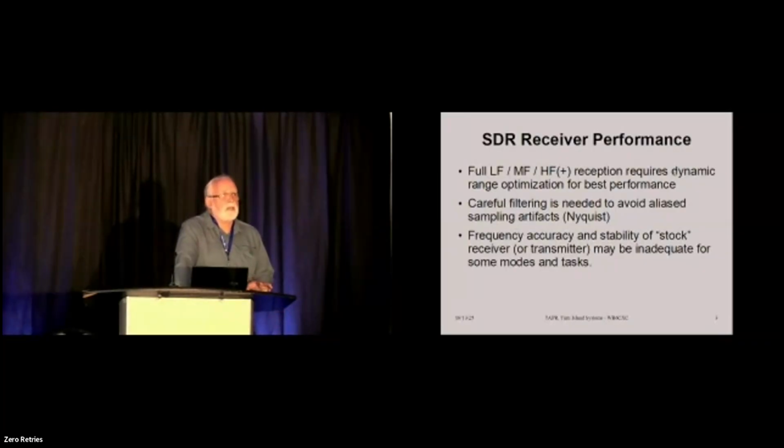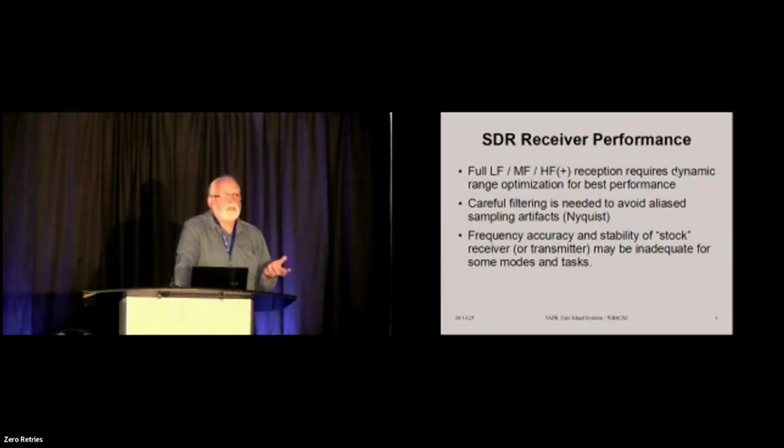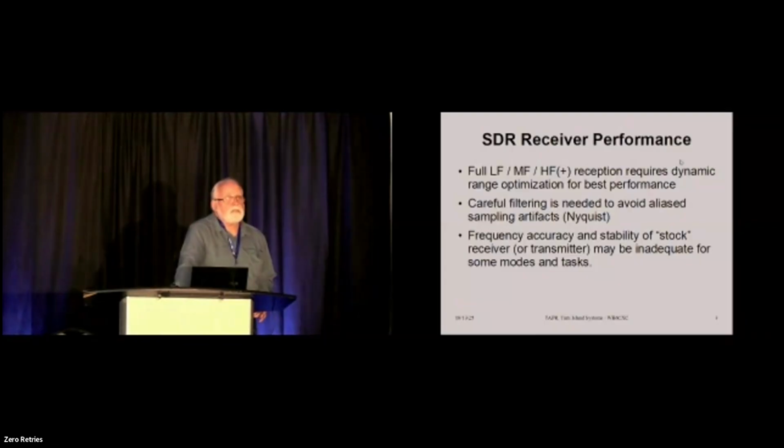And then once you've got that, it's a much easier job to deal with dynamic range. And dynamic range is important because amplifiers get overloaded, mixers get overloaded, the analog stuff gets overloaded, but the digital stuff also gets overloaded. Also, with SDRs, you've got Nyquist, one of my heroes. But you need to understand the Nyquist sampling theorem. We heard you have to sample at twice the highest frequency signal content of your input.